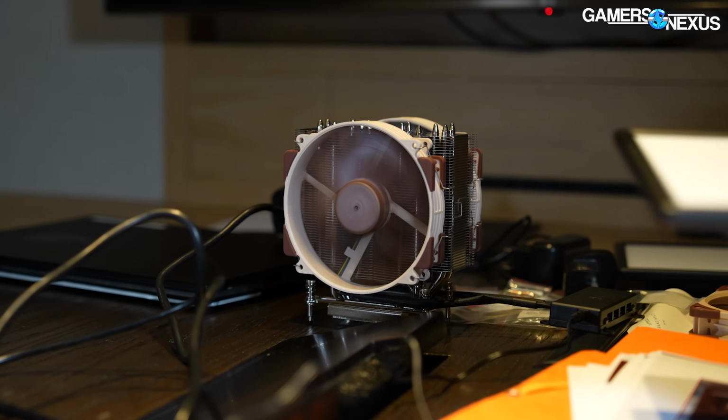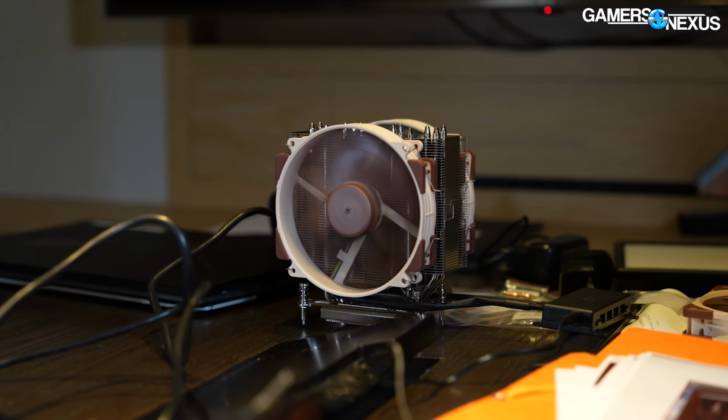Sure, in a certain sense. It dictates the lifespan of your fan. But I would, on the other hand, be very hesitant about making too much of the terms on the box. So I would say you should look at the track record of the manufacturer much more than whether it says FDB, HDB, or sleeve bearing on the package, because there are so many factors that play into what makes a good bearing that are more important than the basic structure.